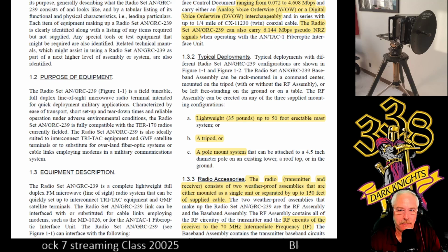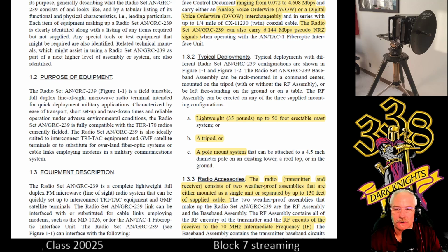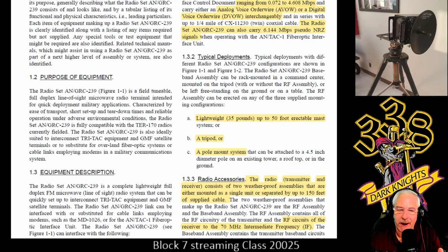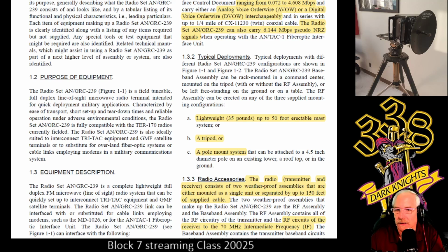There are extra cables and extra stakes. Instead of the 1.5-foot stakes, they come with a 2.5-foot stake. And the extra cables give you extra support and give you 4 sets of guy ropes. So that wind load is about 70 miles an hour with the RF assembly on top of the mast. Anything beyond that, take it down. You'll toast the mast.